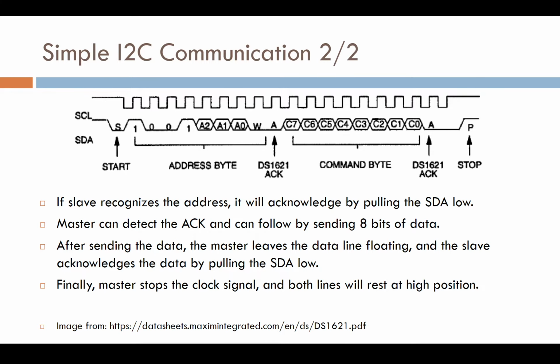Same when you are writing a data byte, the next data byte, again, it's basically between start and stop. The device has recognized this transmission, then it sends a data byte or command byte or as many command bytes as are needed. And after each 8-bit transmission of data, there's an acknowledgement. And finally, the stop sequence. Yep, plenty of small details, and more about that will come in some other hardware related software courses in smart systems.